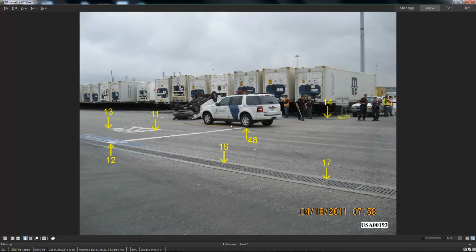Before I go to the site at all, I'll pull up the photograph that I'm interested in. I'll label every point that I hope that we can measure at the time of our site inspection, and then I'll put a number on that point. And whoever's operating the total station will number that point accordingly, so that both of our systems are synced up, and it makes the actual modeling go much easier in PhotoModeler.